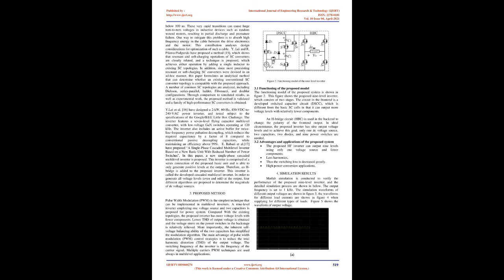However, SC converters have their own issues such as charge redistribution loss and no ability for lossless output load regulation. In this paper we have proposed the use of the FCML converter in high voltage step-up operation. A hardware prototype is implemented, which can convert 100V to 1000V with 820W maximum output power and 94.1% peak efficiency. Comparing to state-of-the-art solutions, the proposed converter has demonstrated a significant improvement on the power density and efficiency, with the inherent advantages of the FCML topology that allow the use of smaller inductors, low-voltage switches and high-energy density capacitors in designing the circuit. 2. Literature survey.